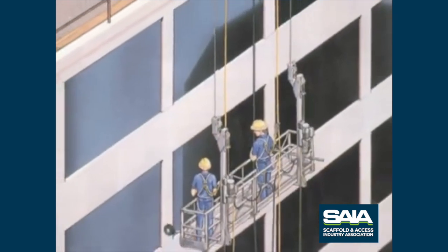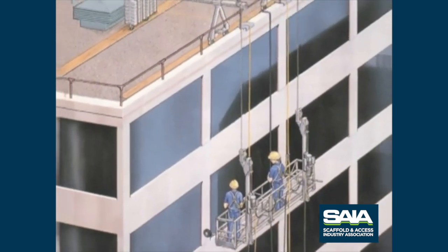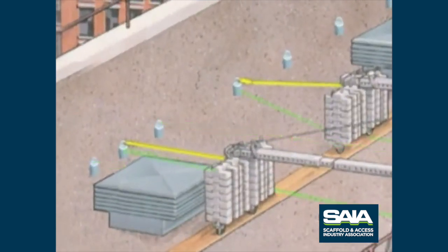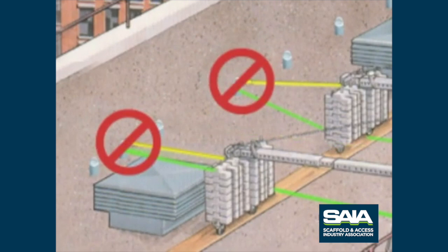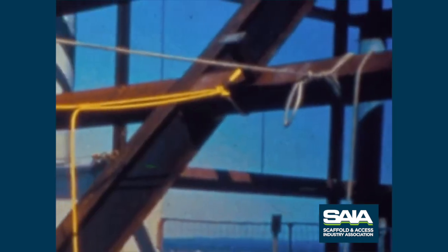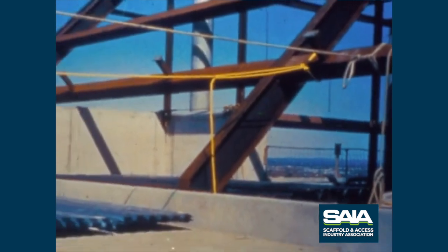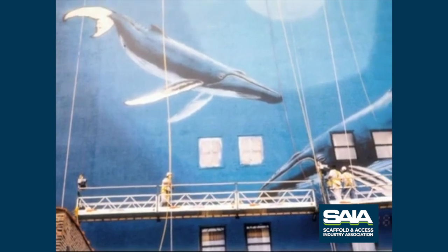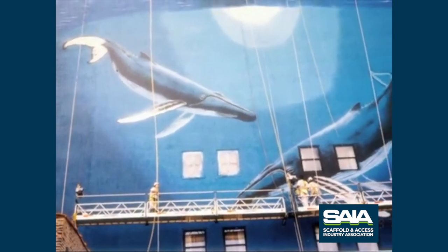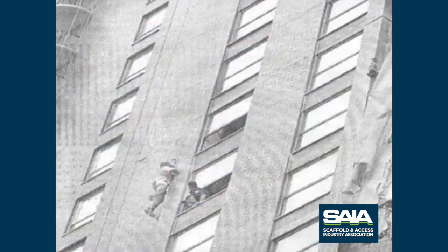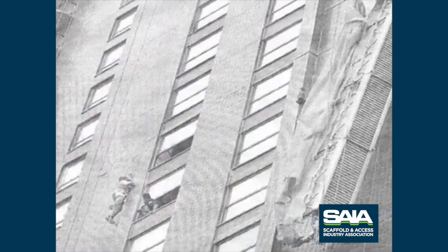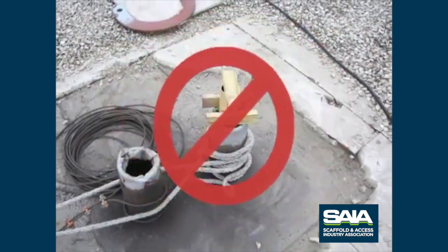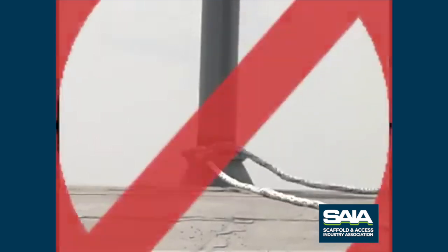Each lifeline must be able to support a worker in the event he should fall. In addition, the lines must be attached to separate structurally sound points. Do not tie off from the same point on a structure to which the suspension device or tieback is attached. Vertical lifelines must be attached to the anchorages that can take the required load. That point may be quite a distance from the rigging. Lifelines should be suspended directly above each worker on the suspended platform. Doing so will minimize the worker's pendulum effect in the event the lifeline is called upon to suspend the worker. Do not tie off to vent pipes, chimneys, or other structures that cannot hold the complete load.